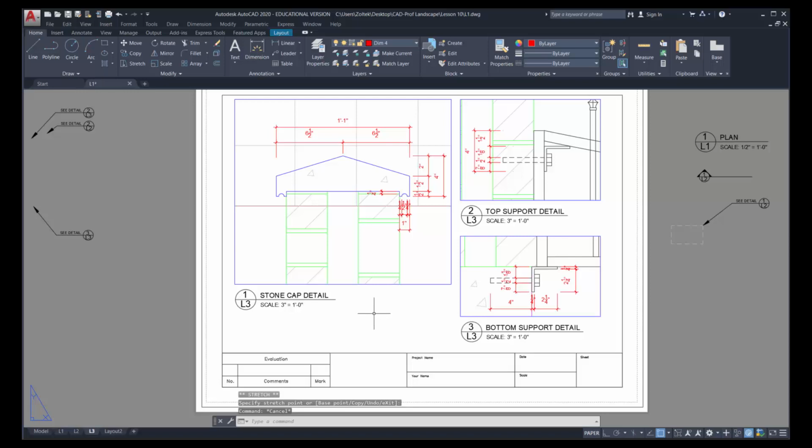So to make multiple viewports, it doesn't take a lot. Now if I leave these in the viewport and I go to plot this or print this all as a mass published document, I can only have the viewports on or off. I can't have them both. So in order to make sure that they're on in the correct pages, I'm going to create boxes around each of these. So I'm in the title block layer, and I will create a box around each one of these items.